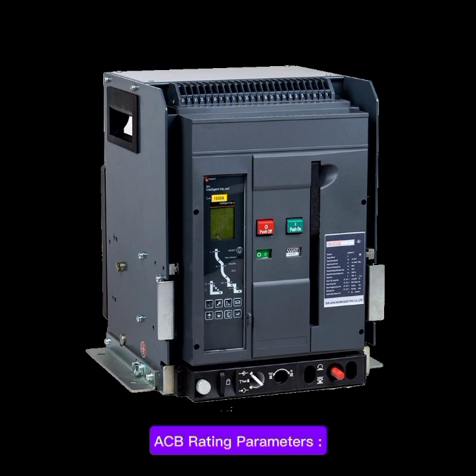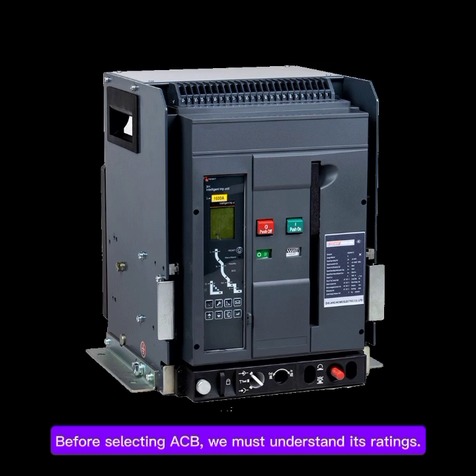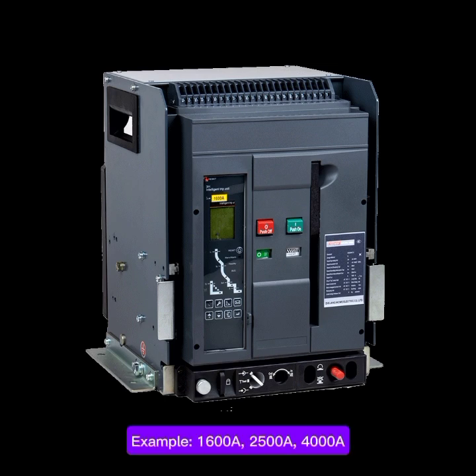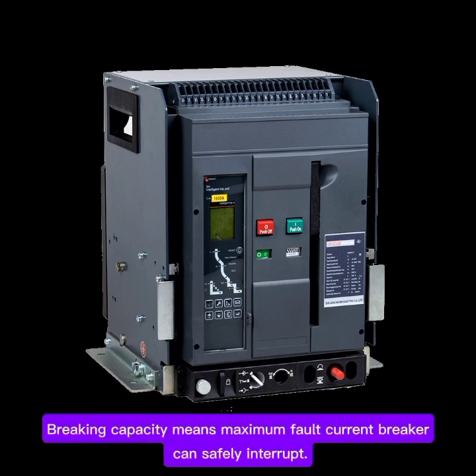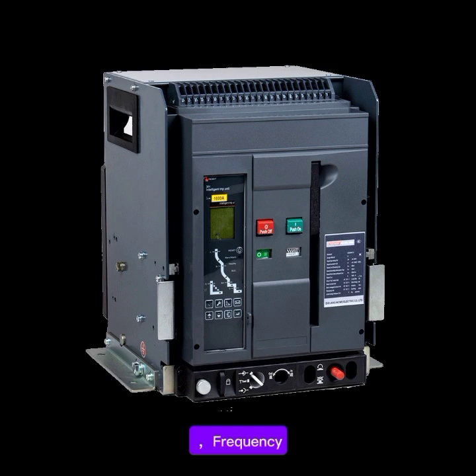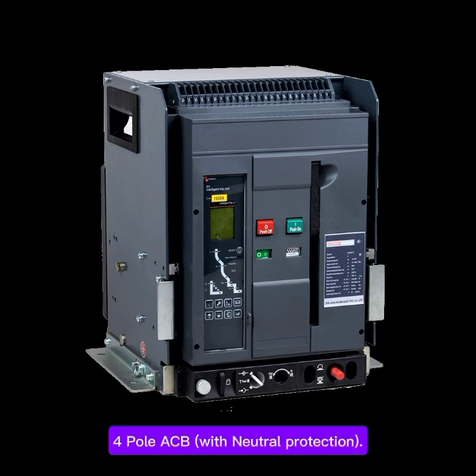ACB rating parameters. Before selecting ACB, we must understand its ratings. Rated current, example 1600A, 2500A, 4000A. Rated voltage, example 415 volts, 690 V. Breaking capacity Icu, example 50,000 A, 65,000 A, 100,000 A. Breaking capacity means maximum fault current breaker can safely interrupt. Frequency normally 50 Hz, 60 Hz. Poles, 3 pole ACB, 4 pole ACB with neutral protection.